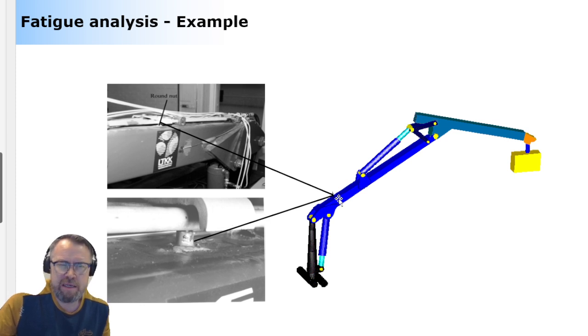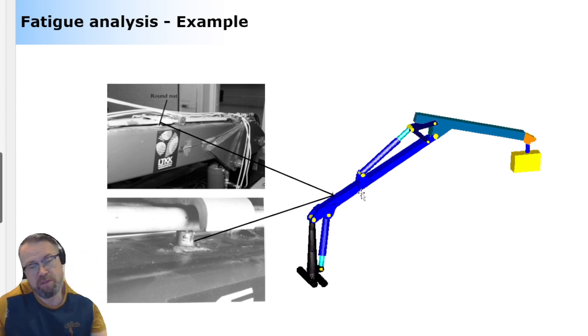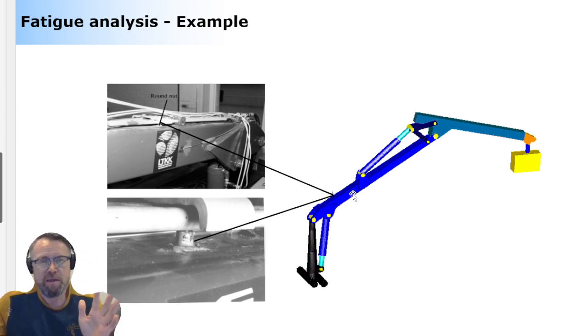And accidentally, this is exactly where these welded nuts are located too. And they don't need to be there because you can put them anywhere else you want. This is a good lesson to learn: whenever you use welding, look where the welding is located and put it away from the highly stressed areas.